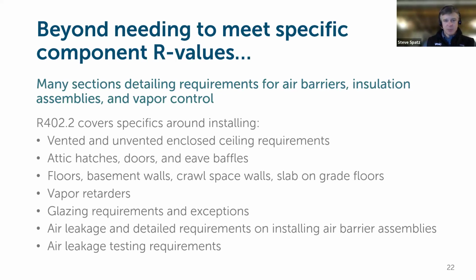These sections of chapter 4 also apply to and are relevant to the other two compliance options. If you're choosing to not go prescriptive and use REScheck or hire a HERS rater, everything in R402.2 that covers these different components and requirements around installation and process and mechanicals, et cetera, are all relevant to any of the compliance options chosen. So this isn't just for prescriptive compliance. What's in this section of the code applies to any compliance type that you're going to choose to use.